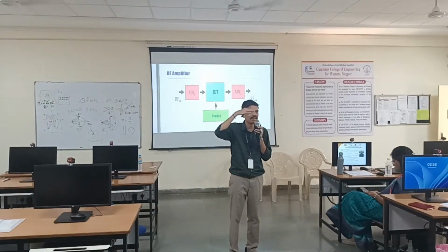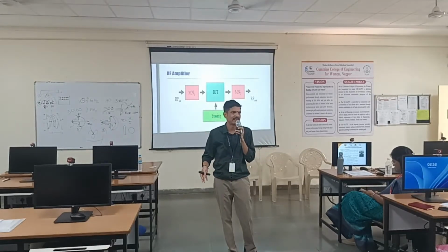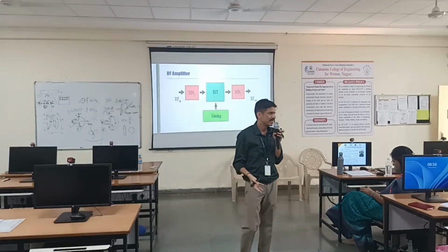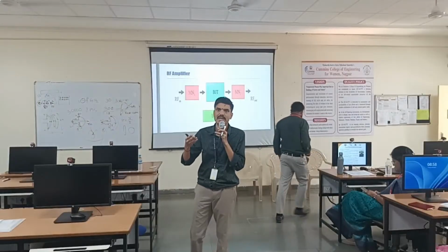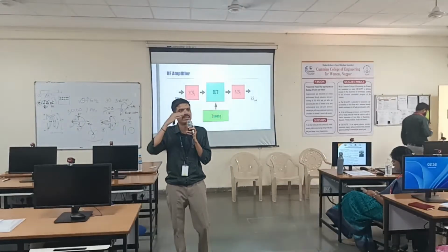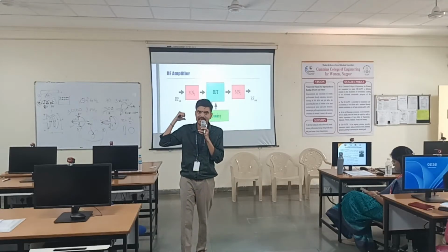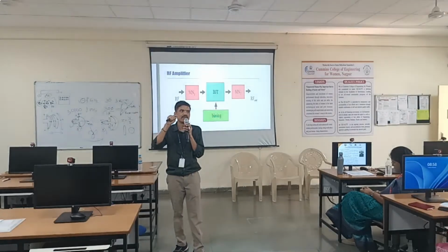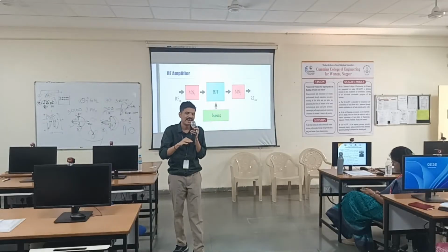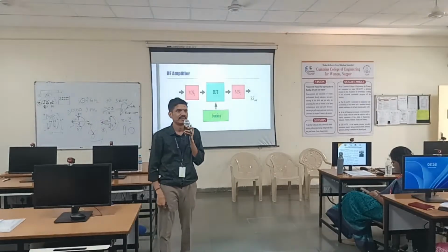The larger is the separation between top metal and bottom metal, more and more fields will come out of your PCB. And that is what radiation. So we want radiation losses as much as possible in antenna design. So the dielectric thickness will be more, that is the requirement for antennas. At the same time, for circuit design such as PAs and all, dielectric thickness should be minimum, which will result in the minimum radiation losses, and you will have a good low loss microstrip circuit.